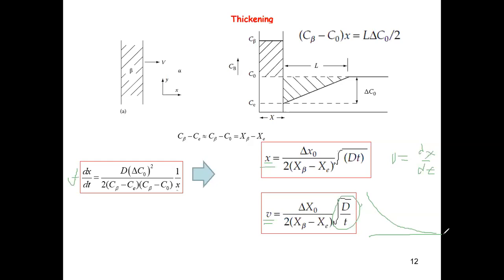But the reality is that way before we get to this point, we stop the dynamics. So this thickening process is typically very, very slow. For most of the time, we won't really have the patience to wait until the atoms all diffuse to the interface, and wait naturally for this process to stop. For most cases, we just quench the system, and then stop there. So the actual dynamics stop way before it naturally stops based on these diffusion dynamics.